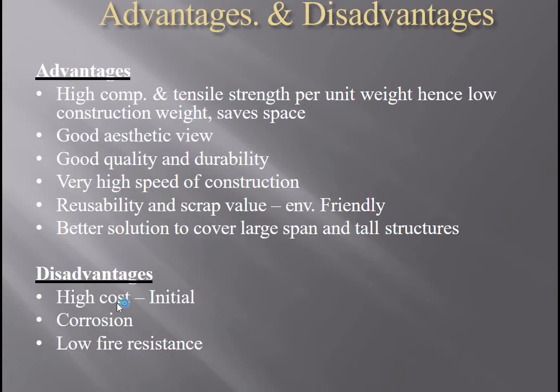Disadvantages: high initial cost and corrosion. Steel is susceptible to corrosion if it is open to the atmosphere. It also has low fire resistance. To avoid corrosion, we have to give some special anti-corrosive treatment to our steel structures.